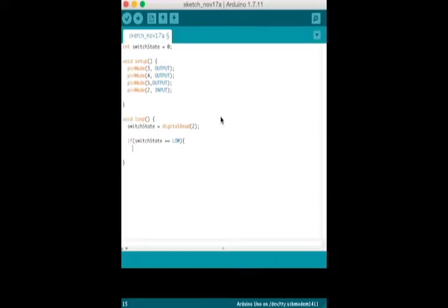If you use only one equals sign, you'll be setting a value instead of comparing it. Okay, so I was right. Building your spaceship. Digital write is a command that allows you to send 5 volts or 0 volts to an output pin. Digital write takes 2 arguments, what pin to control and what value to set that pin, high or low. If you want to turn the red LEDs on and the green LED off, inside your if statement, your code would look like this.